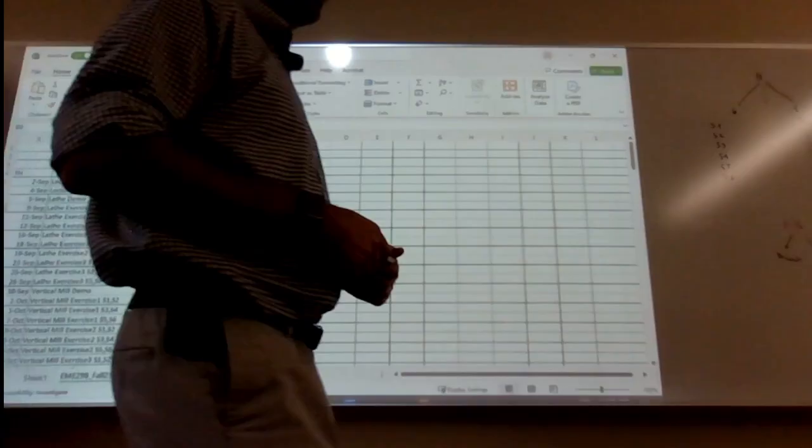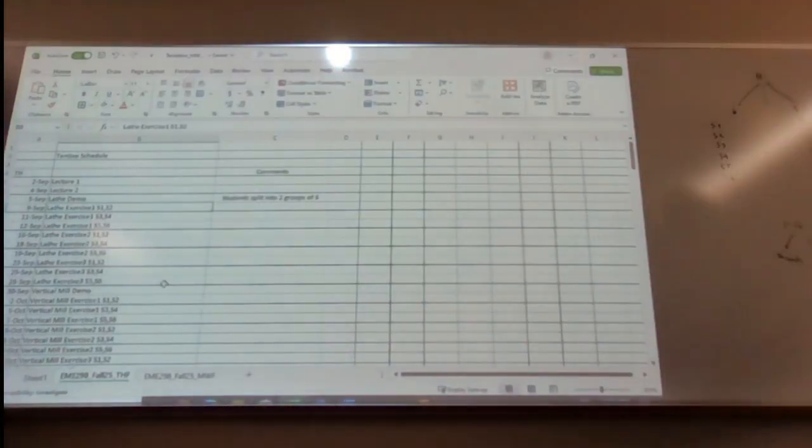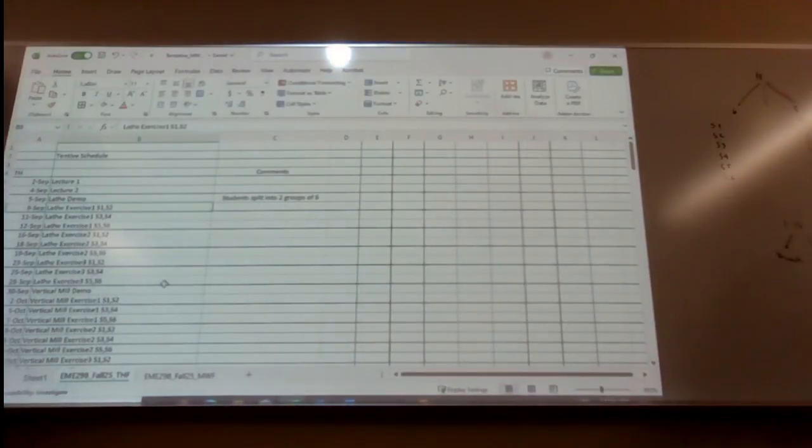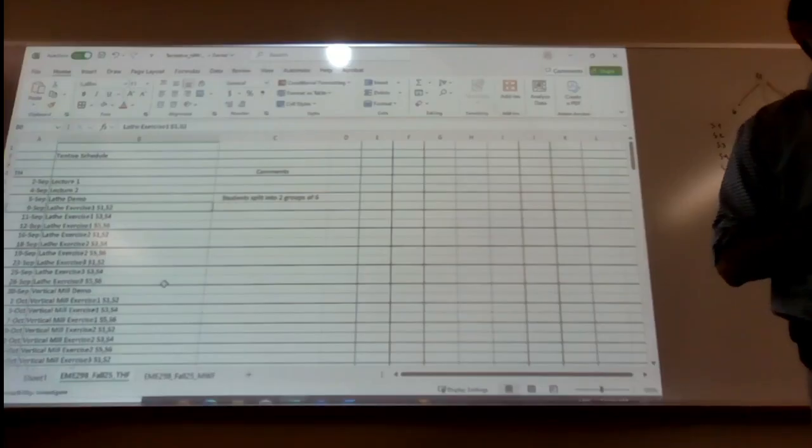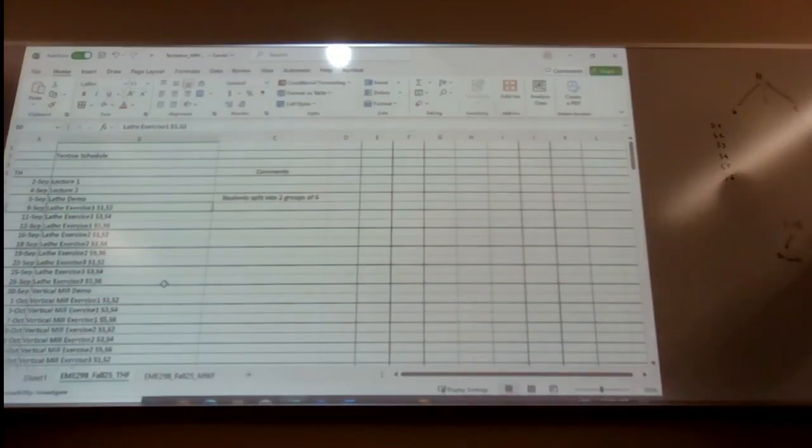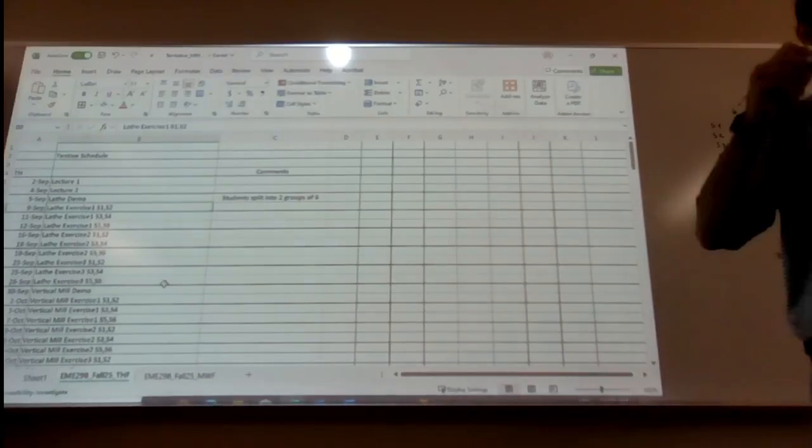A step-by-step means I'm gonna get the stock, I'm gonna deburr the stock, I'm gonna put the stock on the vise. I'm gonna choose the parallel plates. So: acquire the stock, deburr stock, choose parallel plates, and so on. And then you're gonna do step by step of everything that you gotta do.